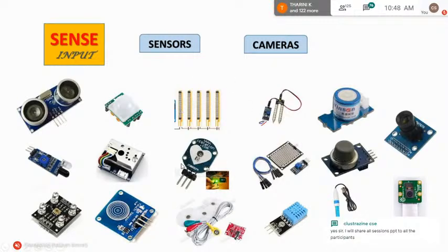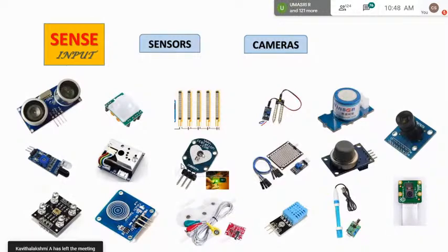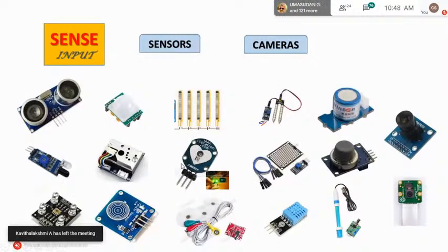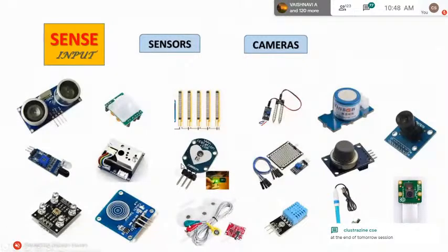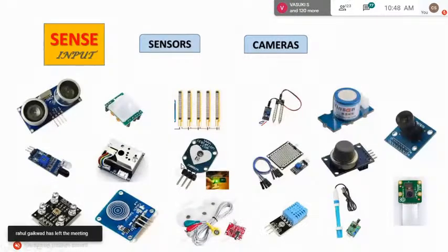And this is the heart rate sensor. If you put your fingertip on top of this one, it will count, and based on your program, it will give you the pulse rate. And this is the ECG sensor you can use. If you put these three LEDs on your chest in the designated places, you can see the ECG on your screen, and based on that, the robot can act.